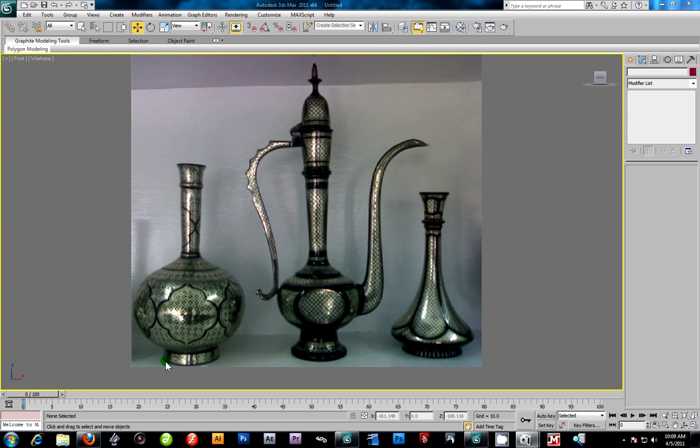The one thing I do want you to pay close attention to is that our reference image is not a true orthographic image. So as you watch me build the spline to this reference image, I'm going to be building it straight down across as if it were orthographic. You never want to match the curve of it.